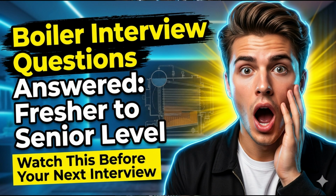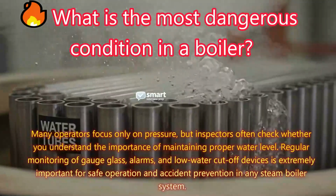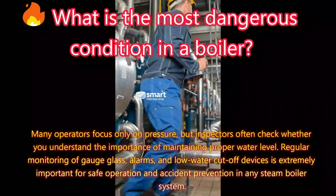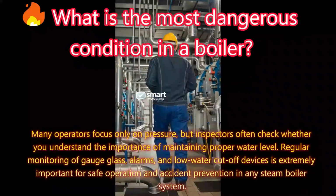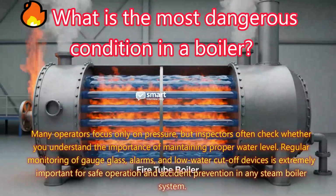Many operators focus only on pressure, but inspectors often check whether you understand the importance of maintaining proper water level. Regular monitoring of gauge glass, alarms, and low water cutoff devices is extremely important for safe operation and accident prevention in any steam boiler system.